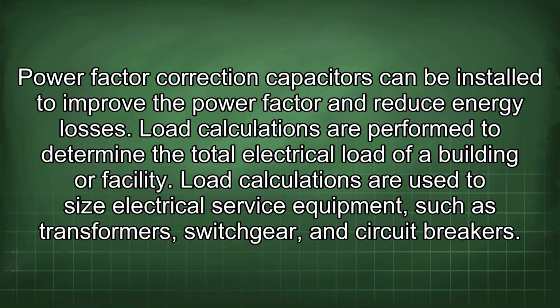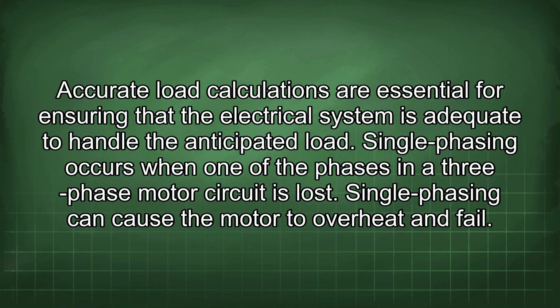Load calculations are performed to determine the total electrical load of a building or facility. Load calculations are used to size electrical service equipment such as transformers, switchgear, and circuit breakers. Accurate load calculations are essential for ensuring that the electrical system is adequate to handle the anticipated load.